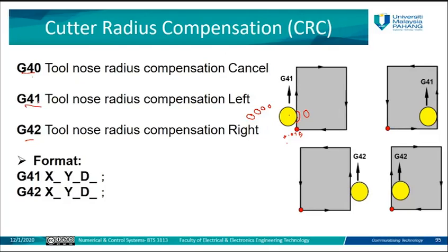If you want G41, G41 is placed on the left. You can see here G41 is placed on the left of the object from outside. Here it's placed on the left of the object from inside. For both we use G41 because it's on the left.